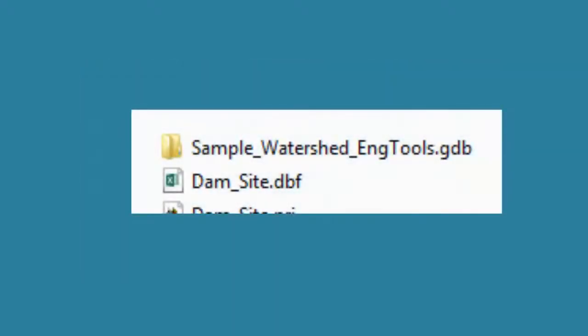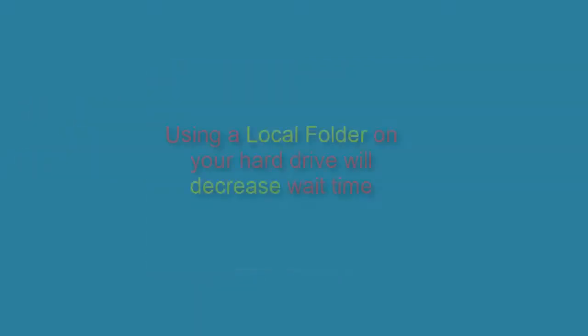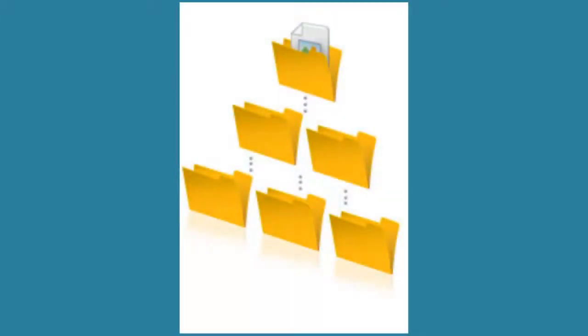All the output files are stored in a geodatabase created automatically by ArcMap. It is this geodatabase that is placed into your workspace folder by the program. It is highly recommended that you choose a local folder without spaces or special characters in the path name. One option is to create a folder on the C drive called something such as Geodata or GIS. However you choose to manage your workspace, give some thought to the organization before you start your project.